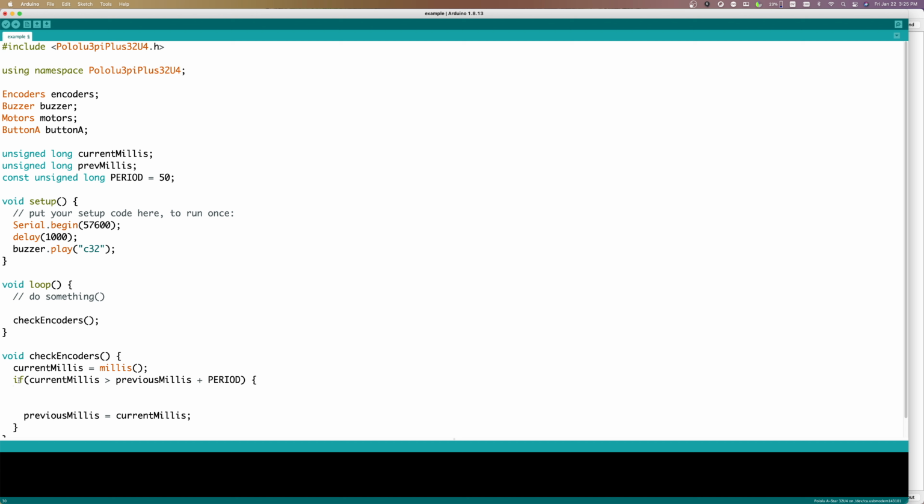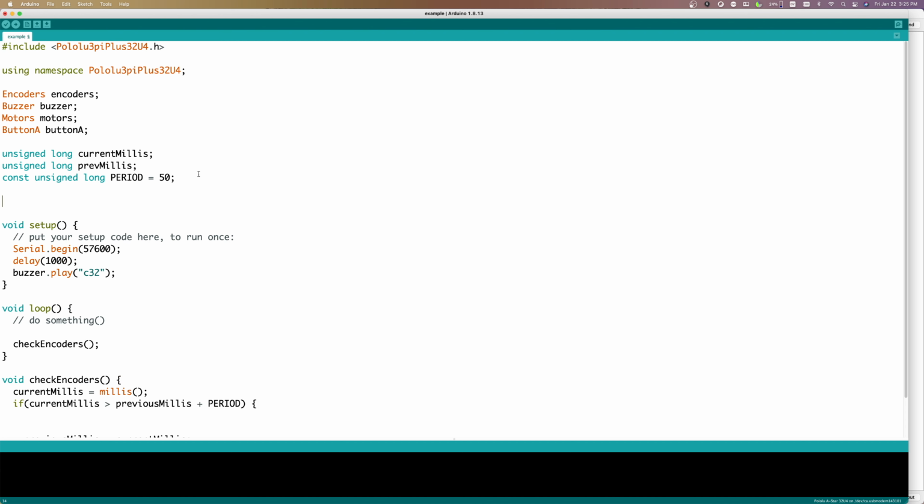The first part of looking at the encoders is again going to be setting up a couple of variables. Now I'm going to actually set these up globally, but they don't need to be, especially in this example. I could actually run all this code right within this method, but commonly in these kinds of things, you're going to be using the results of this in other places, say in a function that deals with using the motors, maybe in some of your other functions that deal with the actual mathematics, localizing the robot. I'm going to create one called counts left.